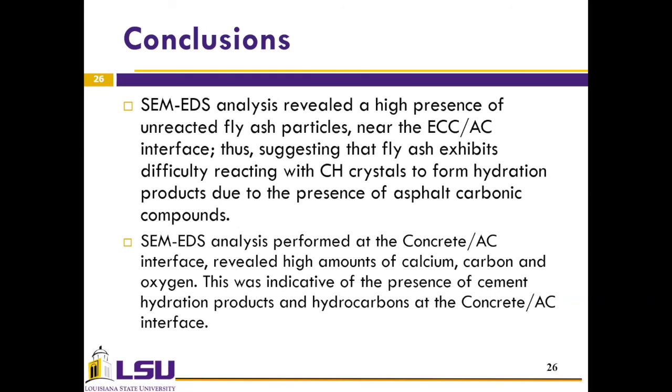SEM EDS analysis revealed a high presence of unreacted fly ash particles near the ECC AC interface, thus suggesting that fly ash exhibits difficulty reacting with CH crystals to form hydration products due to the presence of asphalt carbonic compounds. SEM EDS analysis performed at the concrete AC interface revealed high amounts of calcium, carbon, and oxygen. This was indicative of the presence of cement hydration products and hydrocarbons at the concrete AC interface.